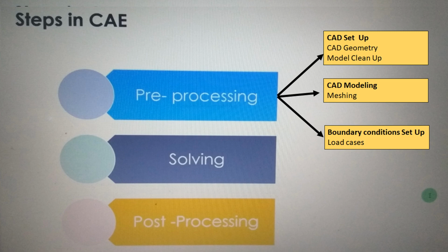In my finite element model, I make sure that I replicate this actual procedure which I am supposed to do on the actual product. I take the L bracket, fix it on one end and give a load on the other side. Now that my finite element model is ready, I give that model to solving. That is where my finite element analysis takes place. It is nothing but the solving phase.